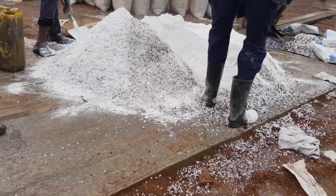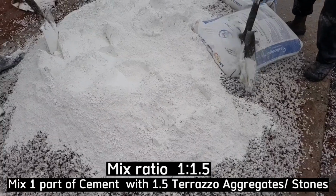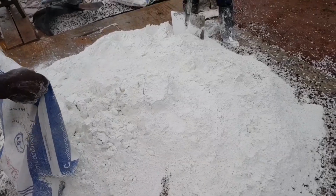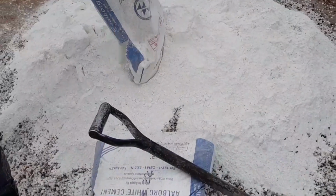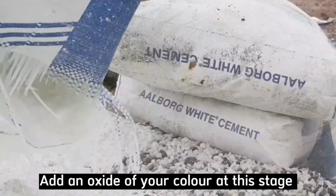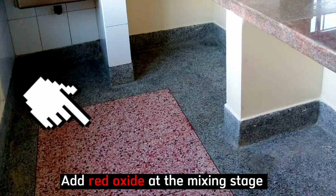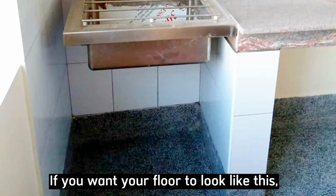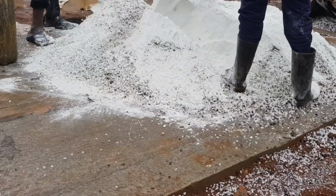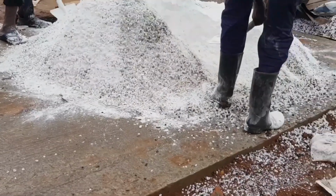The second step is mixing terrazzo aggregates or stones with cement. The general mixing ratio here is 1 to 1.5. That is 1 part of cement and 1.5 aggregates. We normally mix 1 bag of cement with 1.5 flat wheelbarrows of aggregates, or mix with 3 basins of aggregates or stones with 1 bag of cement, and later mix with water. You may add an oxide of your favorite color at this stage in the mix. For example, if you want your floor to look like this, simply add a red oxide in the mix at this stage. If you want your floor to be black in color, simply add a black oxide at this stage in the mix. In other words, you add an oxide of the color you want your floor to look like at this stage in the mix.